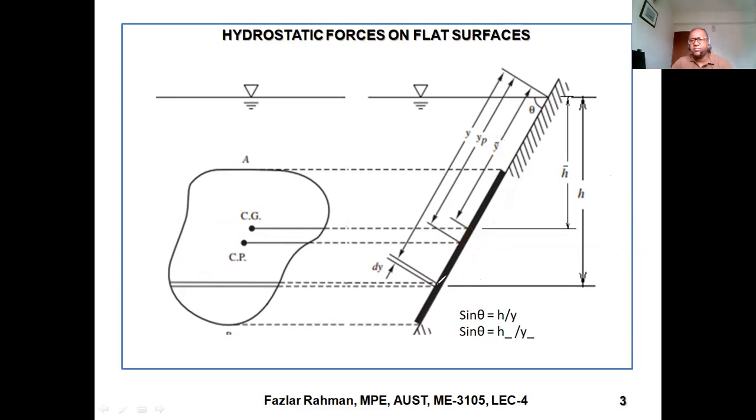Okay, now this small strip is dy. The vertical height at the bottom we are saying is h. What will be the height over here? Less than h. But we are considering an extremely narrow area, dy, a small segment, so we are not considering that difference. So how much will be the fluid pressure in that small segment? Fluid pressure we can figure out: P equal to rho g h, or we can say gamma h.